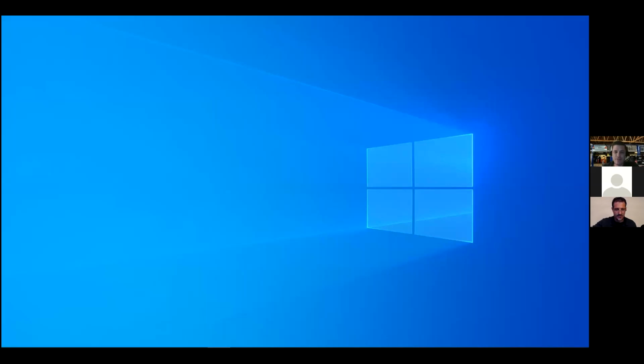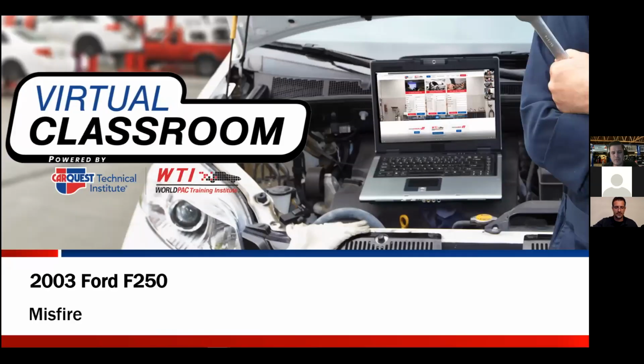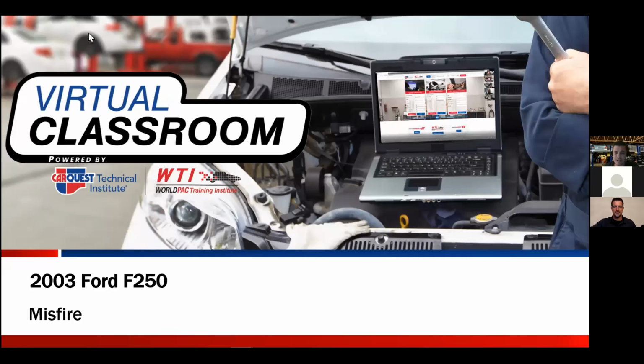Amongst the 3 main scopes that Brandon has brought up through this 8-hour session, ATS, Pico, and Snap-on, the ATS, Automotive Test Solutions, eScope, is the only company I know of that is using these vacuum transducers, but they're absolute pressure transducers. So they don't just produce a voltage based off the change of pressure. It actually is an absolute sensor. It's different in the fact that voltage rises when pressure decreases and voltage falls when pressure increases.